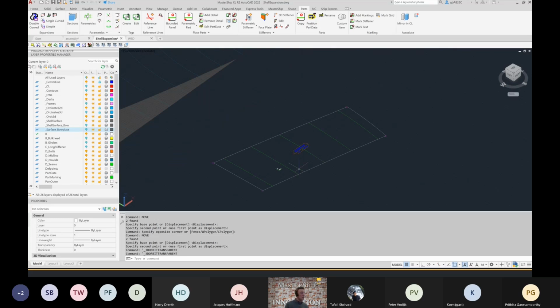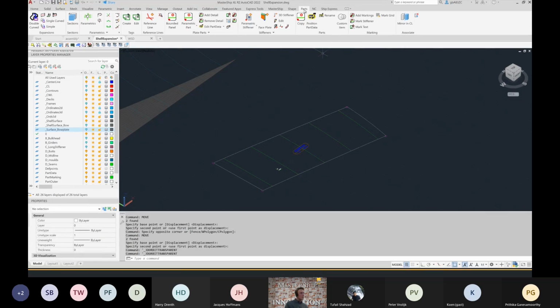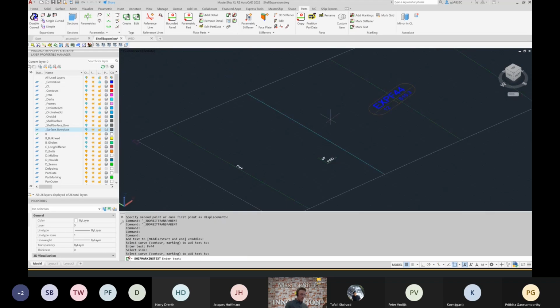But before we do so, we can apply maybe some more markings. So we can indicate the frame lines. We can indicate some modifications to be made, for example, beveling. My computer needs a bit of time to think. Ah, there it goes. So we can go to mark text. Then we select, for example, this line, and we say frame 44. We place it here. Let's do a second, frame 45, etc.